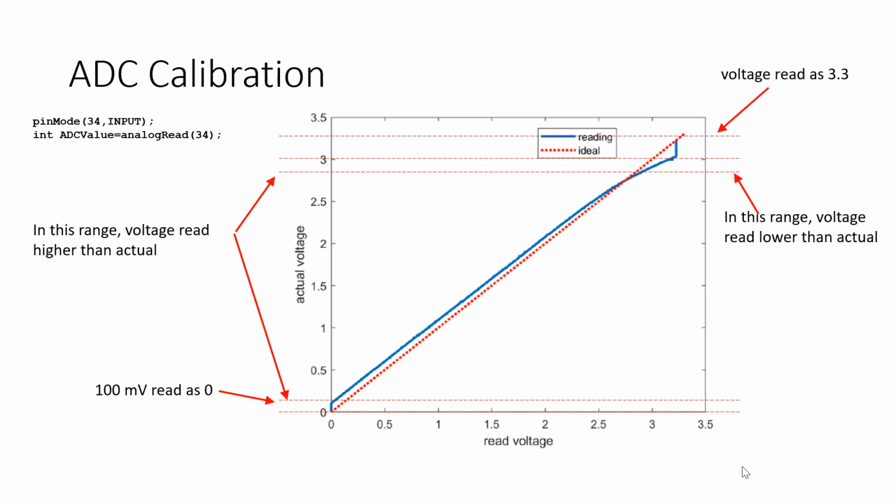This calibration is something you would only run the first time you get your new supply, be it a new battery or a new... Yeah. So the way it's worded in the lab sheet, every single time you run your code, it's going to run through that. But of course, if you want, you can make it a little bit more robust than that. You could have the user type a command or something to put it into calibration. But I'm fine with that. I don't care. You don't have to have it run through the whole calibration every time you boot, right?